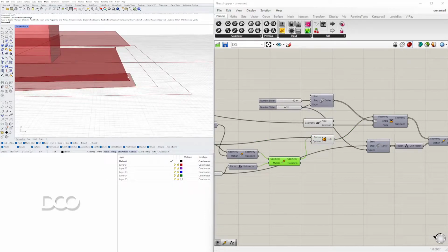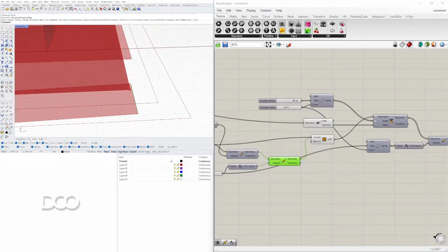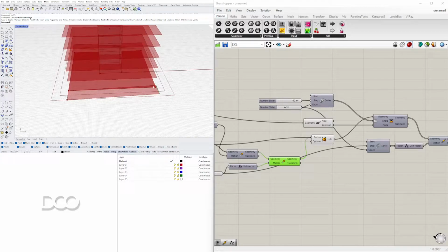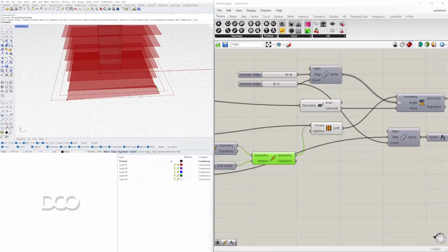Now remember that we have created this line segment to create this ramp. Well, we are going to take that line segment and we're going to extrude it in the X direction by the same amount as that this is between those 2 points.